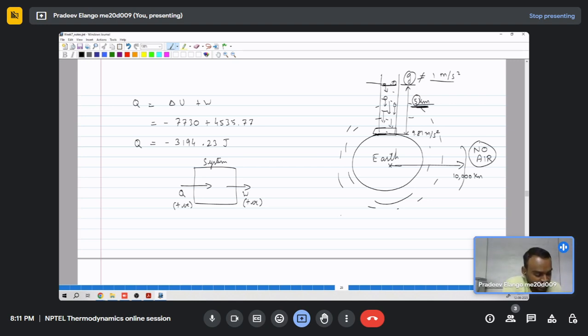So now pressure, as we studied earlier, is rho g h. Rho of air is 1.18 something. Gravity, the effective gravity we can call it, is something like 9.81 near the ground, but as we go upward it is not 9.81, it is decreasing.